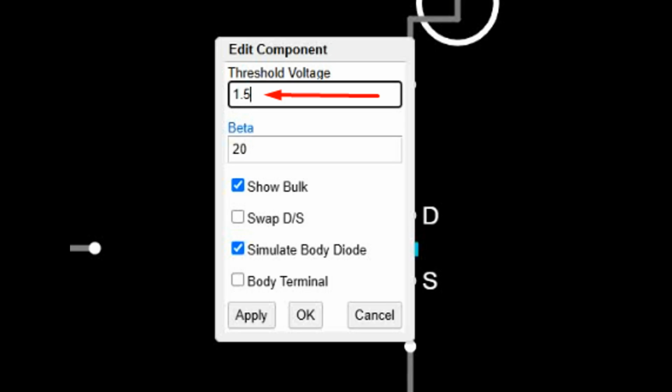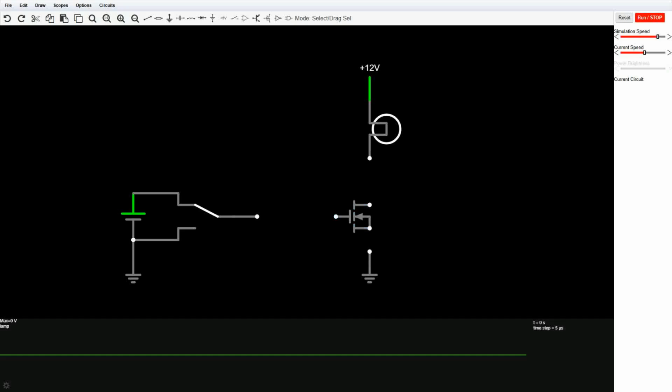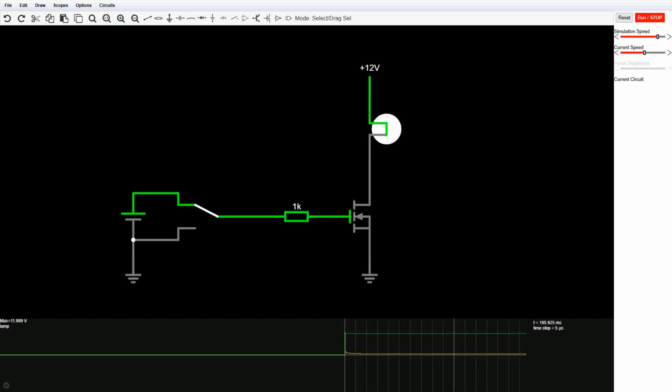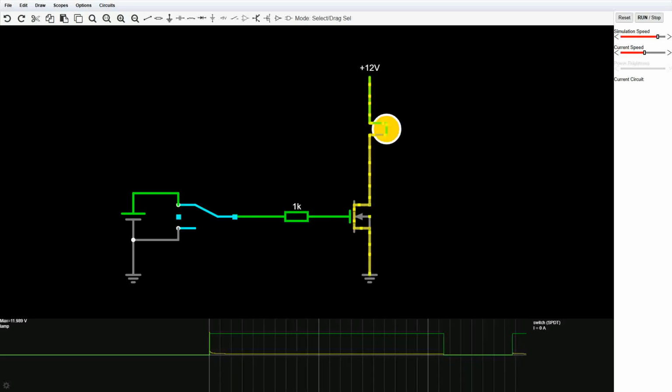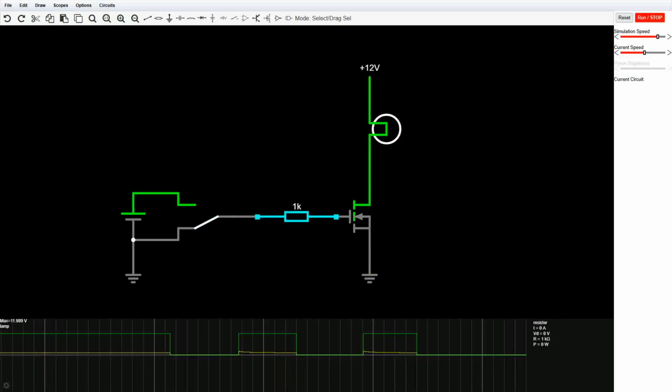Logic level MOSFETs work with 5 volts or 3.3 volts and can often be driven directly from a microcontroller. Sometimes you add a resistor to limit gate current spikes, because the MOSFET's gate still eats a significant current just to charge up. For stronger high current MOSFETs, you may need near 10 volts at the gate. You can use a small bipolar transistor to supply it.